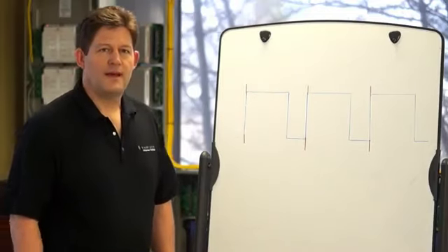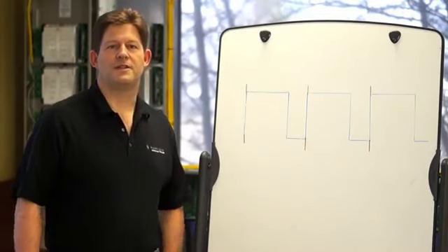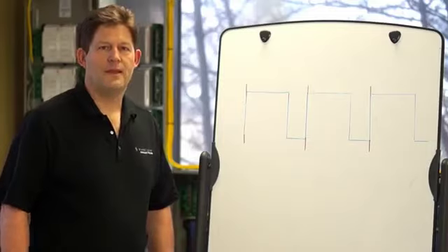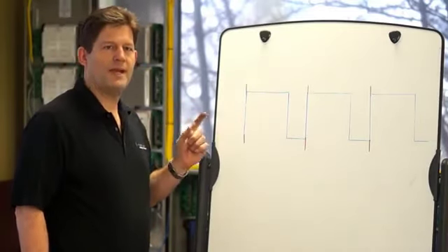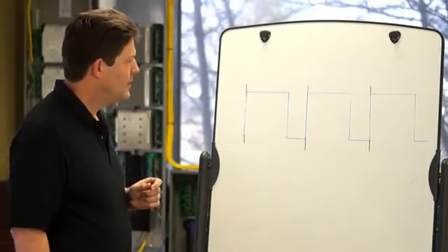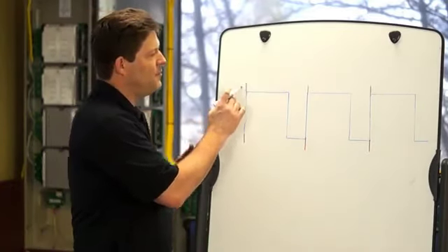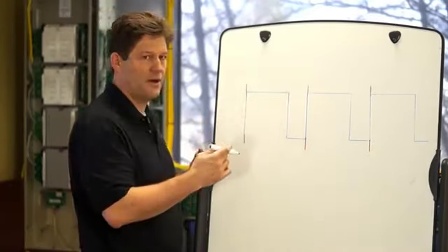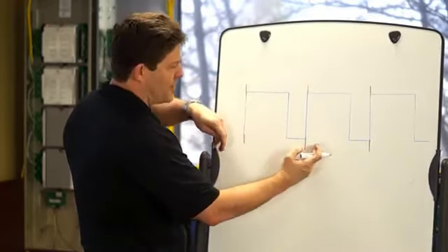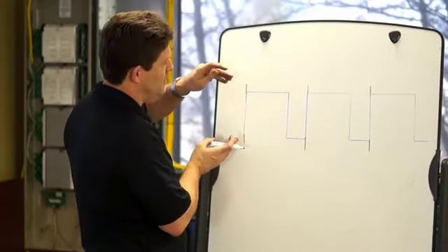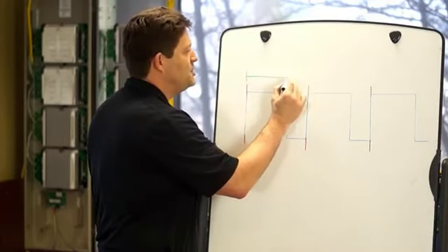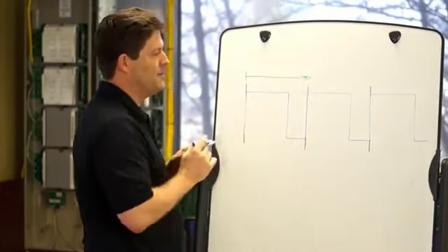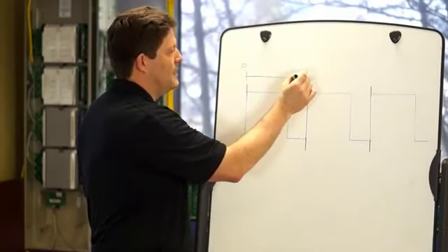A second method of analog indirect dimming is pulse width modulation, or PWM. In PWM, a constant voltage, repeating square wave is the control signal. The percentage of the time that the voltage is on is actually the variable. We don't change the frequency, we don't change the voltage, we just change the duration that it is on, and that goes between 0 and 100%.